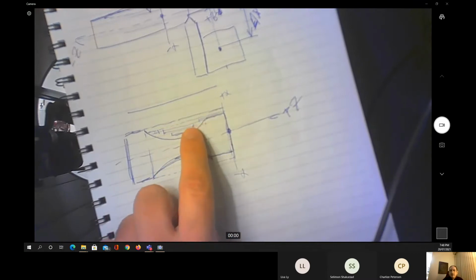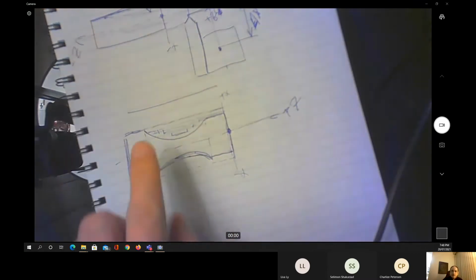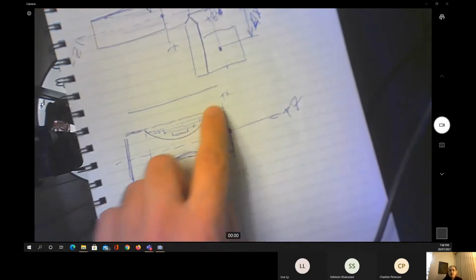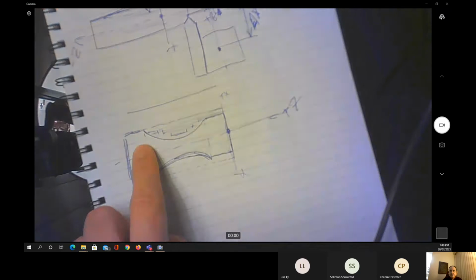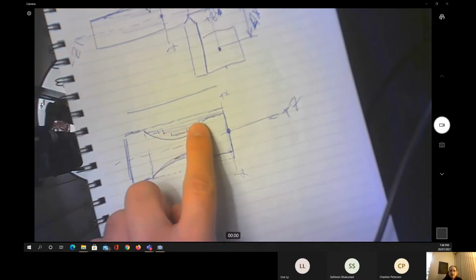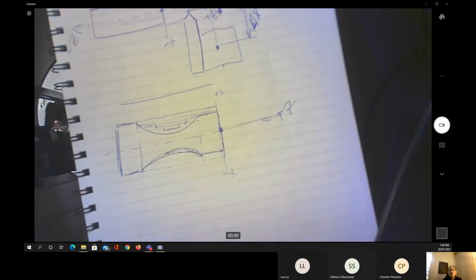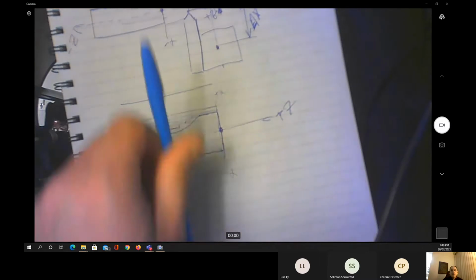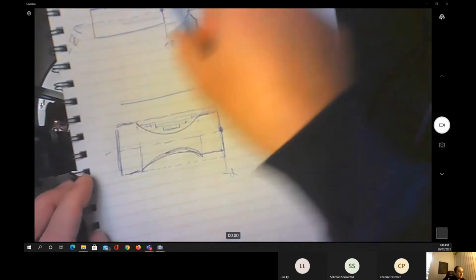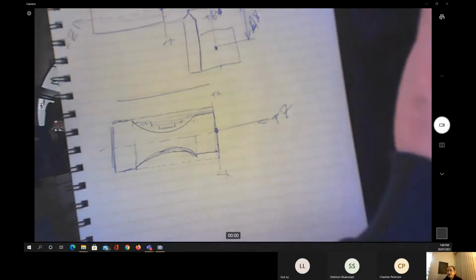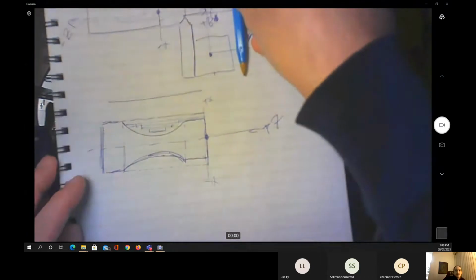And this will be at the beginning. And later I'm going to do the final cut to make the arc. So to do that, I once again need to sketch these lines and find the intersection points. And this intersection point is going to be the point that the cutting tool is going to move to. The movement we're going to have in the turning operation is going to be as following.